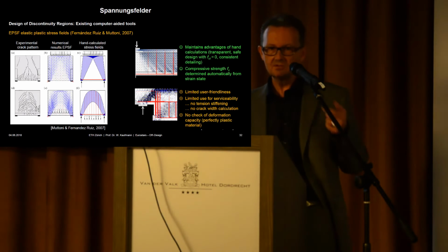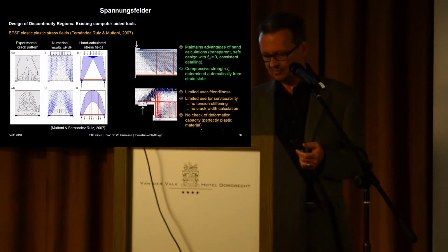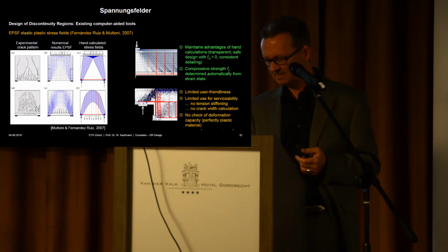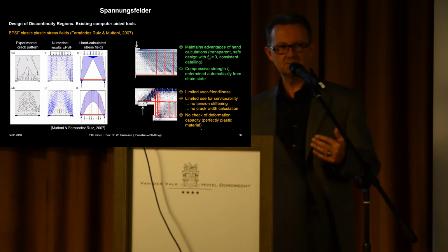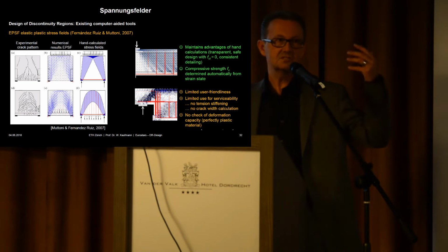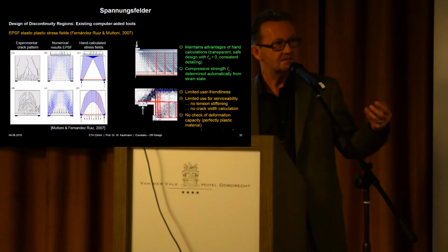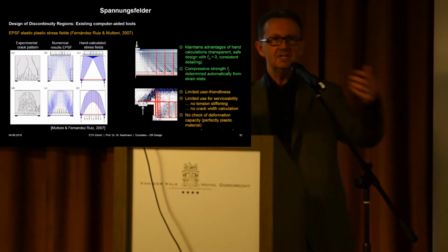Integral of sigma over epsilon or integral of epsilon over sigma turns out to be the same. And in this lower case, if the load is applied on the bottom, the vertical stirrups are very flexible compared to the concrete. So the program only wants to activate them over the length that is strictly needed, and this is enough. So even if the stirrup goes up there, it's not being activated because that would give a softer response. But the program finds that automatically. So does the StatiCa. It's just implicit in the method inside. So that helps you to find the right solution of the infinity of possibilities.